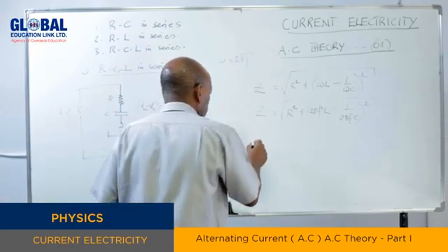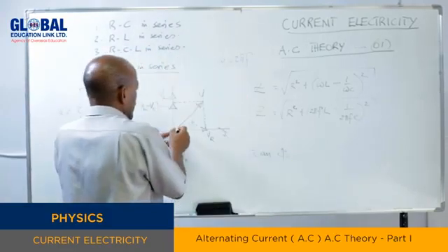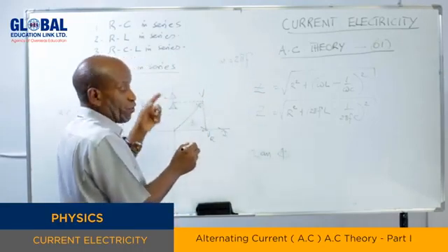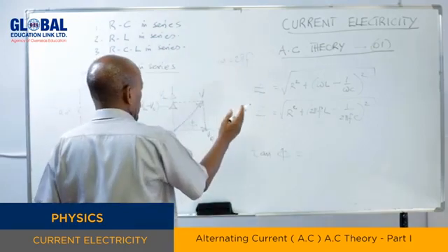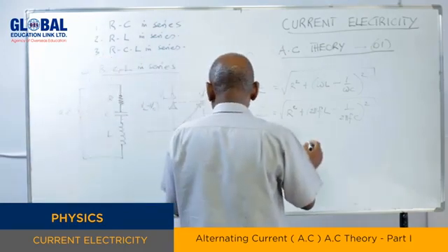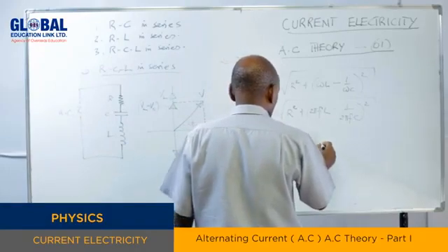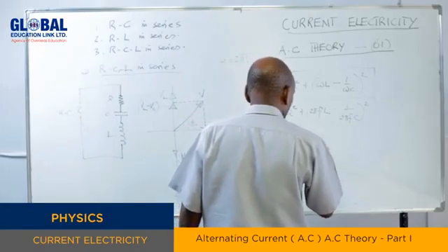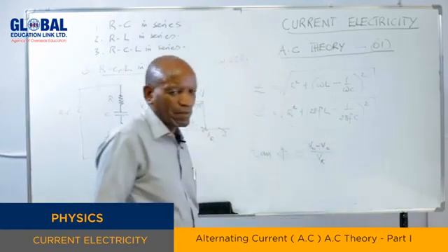And as well, we can get the angle at which the applied voltage V across the combination acts. So tan theta will be the opposite over adjacent. The opposite is the resultant of the voltage through an inductor and the voltage through a capacitor, over the voltage through a resistor.